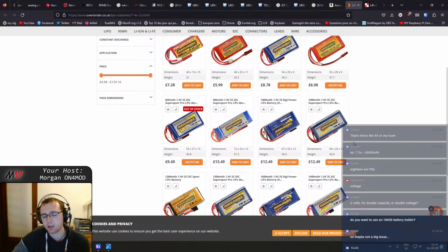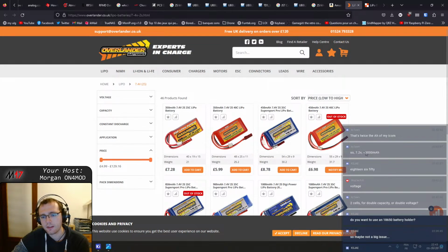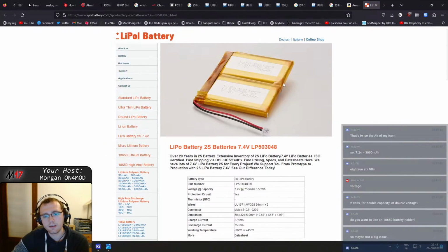You need a specific charger with the correct connector, or you need to fit a specific connector, and then we are going to have batteries with 2 pins, some with 3 contacts, and then it's a mess. So I would say a 2-cell lithium battery holder is the way to go, at least for the proof of concept, for now.